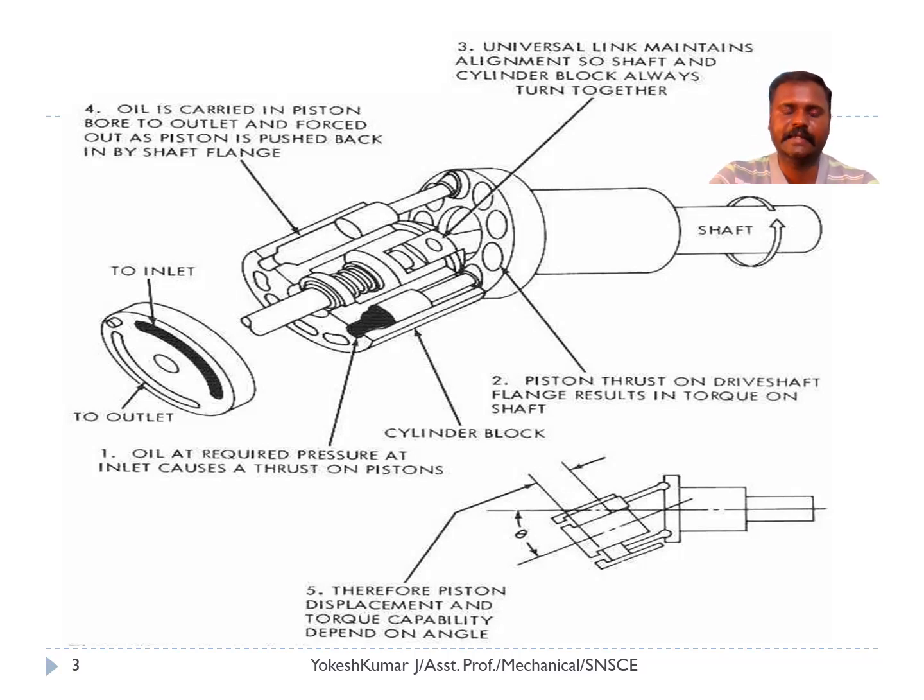So the oil is collected at the outlet and further it is bypassed to the reservoir via the direction control valve. The maximum speed of the motor can be accomplished with the maximum inclination angle, and if the inclination angle is zero, the motor will come to rest.